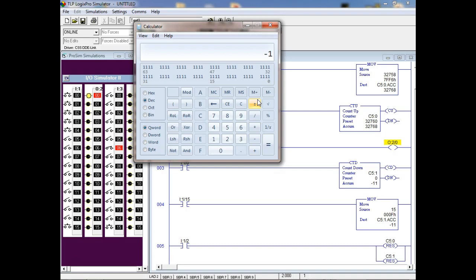So when we're dealing with this number system, we call it 2's complement, which we'll learn more in detail. If you look at the most significant bit right here, if you see it as a 1, it's interpreted as a negative. I can put any positive number into the range of this guy, and it's got a big range. So I'm going to put 135. What you notice about the most significant bit for any positive number is that it will be 0. For any negative number, it will be a 1.